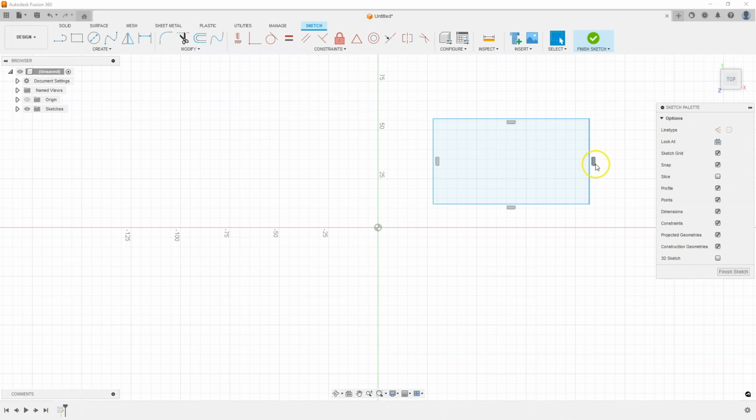These constraints determine whether a line is vertical or horizontal, and this means that there is some kind of limitation placed on these lines, and you cannot slope this line. These lines will always be horizontal or vertical. Only removing the constraint will allow the line to slope. And to delete a constraint, select the constraint and press the delete key.